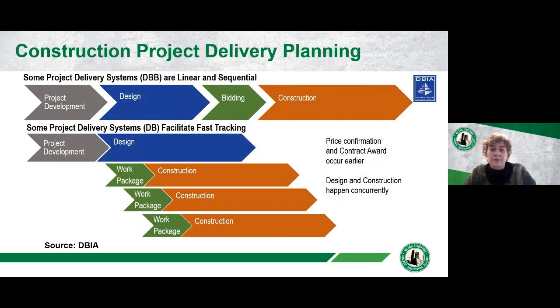When it comes to the planning side, a key difference between design bid build and design build is how the work takes place. When you have a design bid build project, the work has to take place exclusively linear and sequential. The project has to get developed, design moves forward. Once the design is completed, then construction bid documents are created, then the project is awarded, and then construction begins.